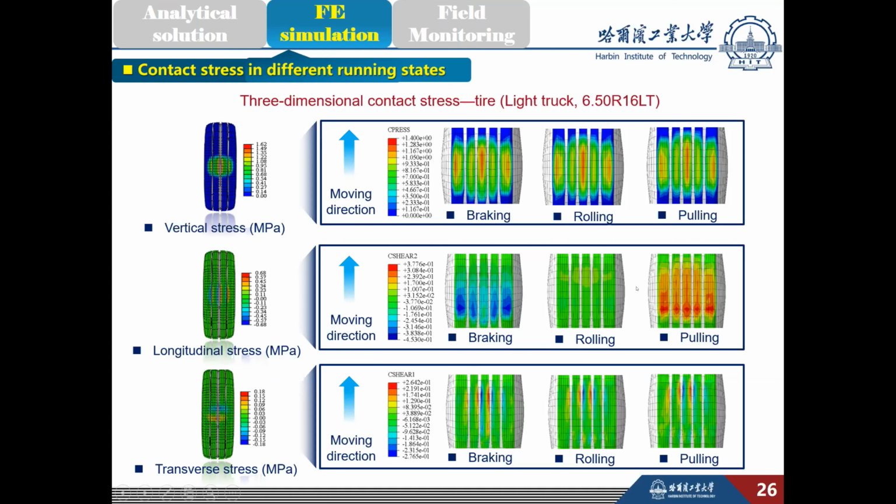Time histories of stress and strain in three directions were presented here. From the results, we can find that the existence of horizontal loading has a great effect on stress and strain histories. To be specific, for this case, the peak values of longitudinal and transverse stress reduced around 10%, while the strain increased around 20 to 30%.